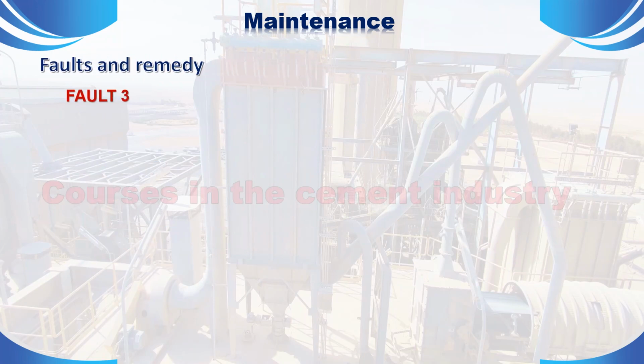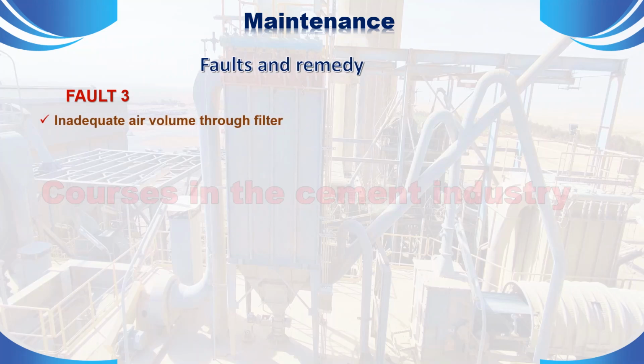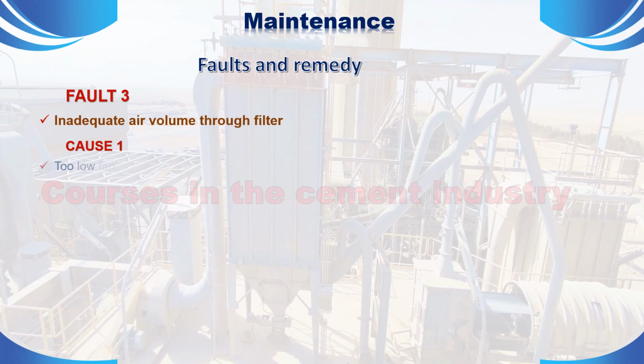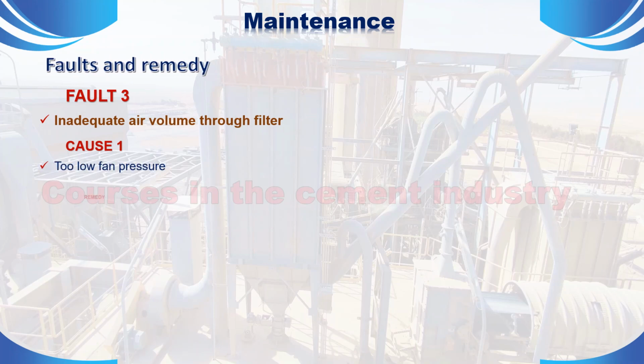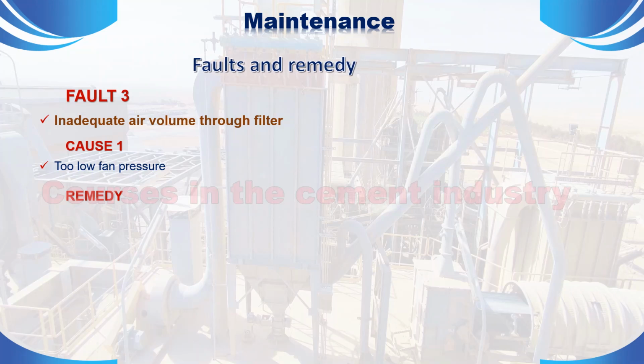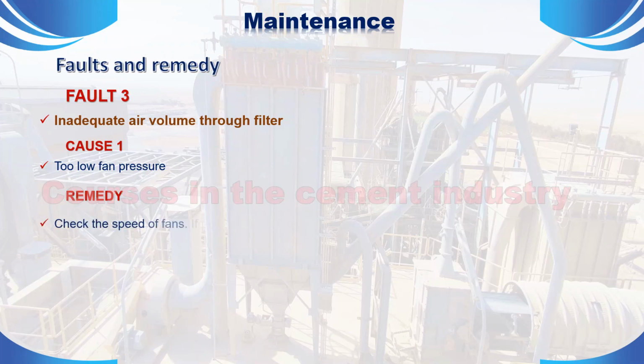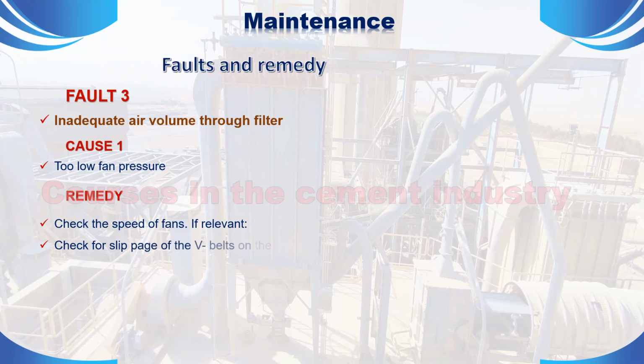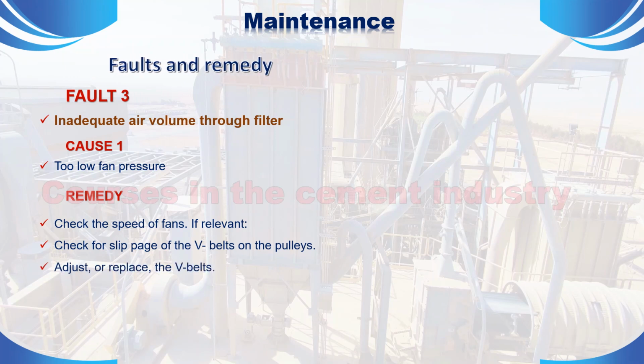Fault 3. Inadequate air volume through filter. Cause 1. Too low fan pressure. Remedy. 1. Check the speed of fans, if relevant. 2. Check for slippage of the V-belts on the pulleys. 3. Adjust or replace the V-belts.